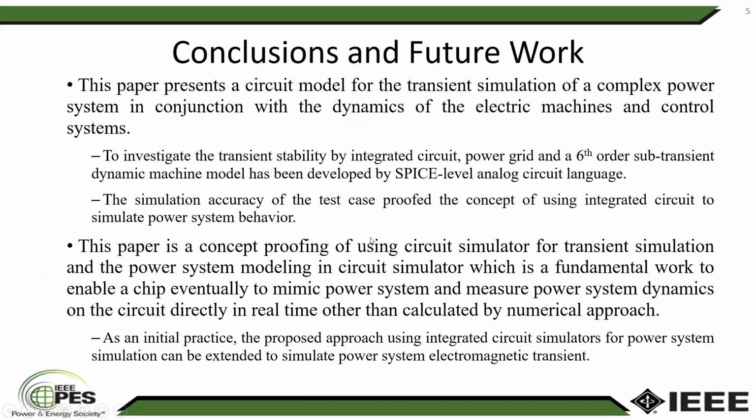So to conclude, this paper proposed a circuit model for transient simulation of a complex power system in conjunction with the dynamics of the electric machines and the control systems. This paper is a concept proofing of using a circuit simulator for transient simulation, and is a fundamental work to enable a chip to mimic power system and measure power system dynamics on the circuit directly in real time, other than calculated by a numerical approach.